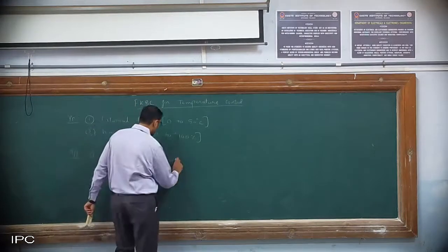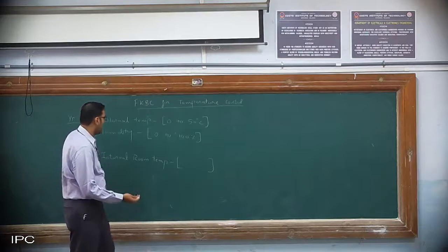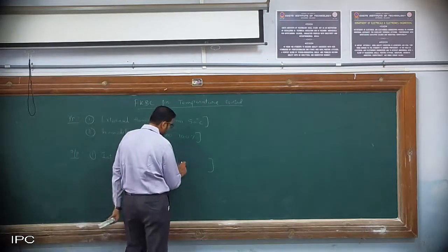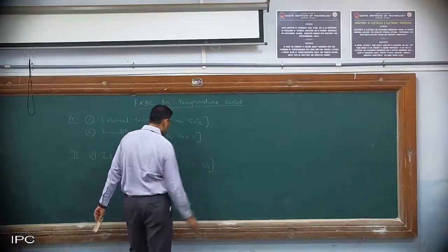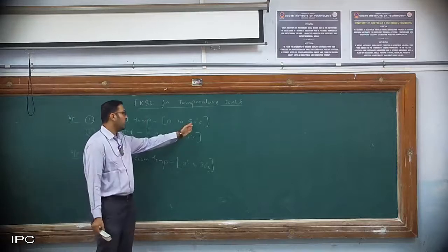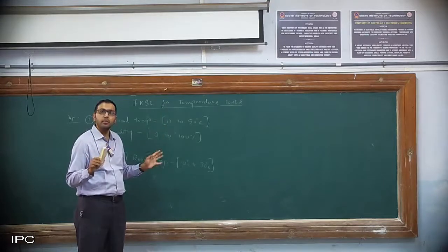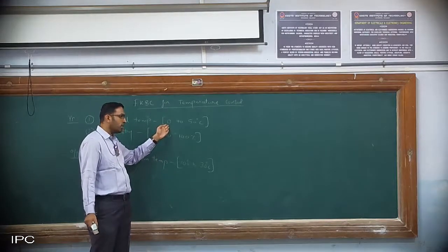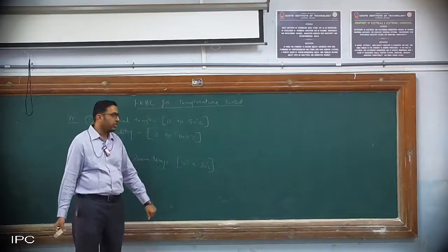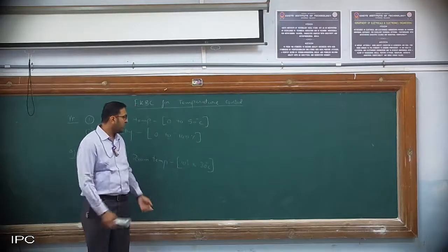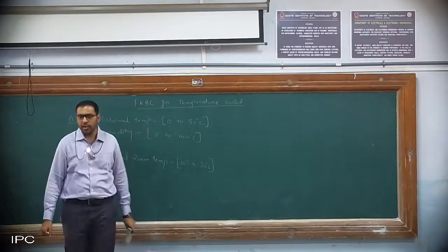Next, again, room temperature. What is the temperature band which we require always? We require a temperature band from around 10 degrees Celsius to 30 degrees Celsius. If the temperature is around 50 degrees outside, we will set it to 10 degrees so that the ambient temperature is pleasant. Suppose it is 0 degrees, so it is chilling, so we need to increase the room temperature. We will set it to around 25 to 30 degrees. So that is the range we have selected, 10 to 30 degrees Celsius. These are the input and output parameters which we have decided.